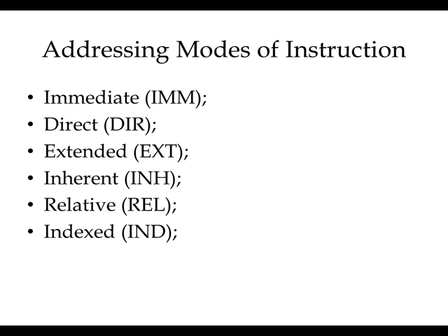But just by looking at the instruction, how do we know what the mode is? For example, the LDAA, have you seen the LDAA just before this one? LDAA has an immediate mode, a direct mode, an extended mode, and an indexed mode. Now, just looking at the instruction, how do I know if this is an immediate mode? So this class tonight, we'll try to learn how to know what the mode is.